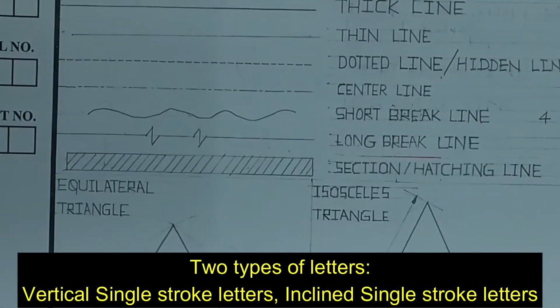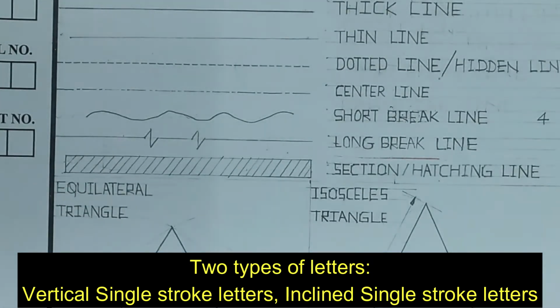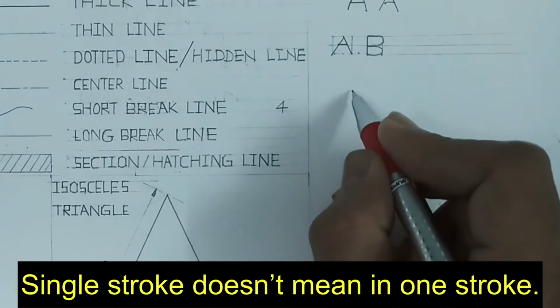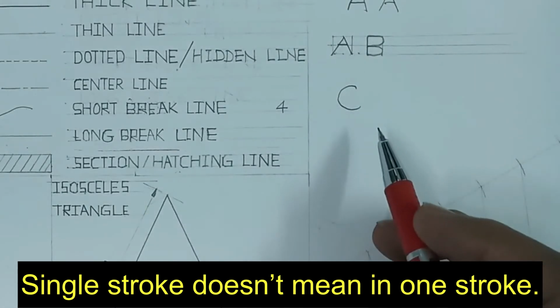Now let us go to the types of letters. In engineering drawing, we generally use two types of letters. One is called vertical single stroke letters and the other one is inclined single stroke letters. Now what is the meaning of single stroke letters? Single stroke doesn't mean that once we start writing, we have to complete a letter in only one stroke. That is not the meaning of single stroke.